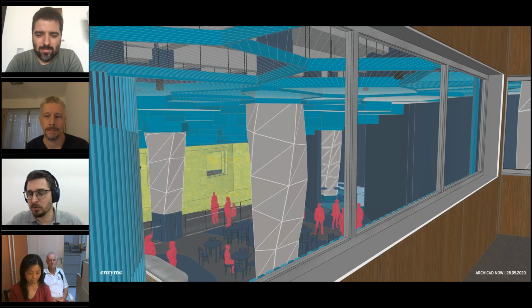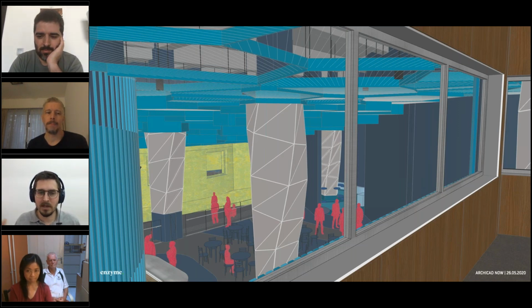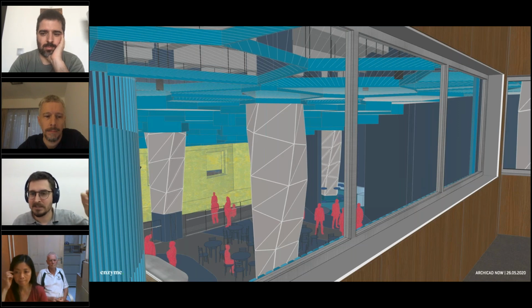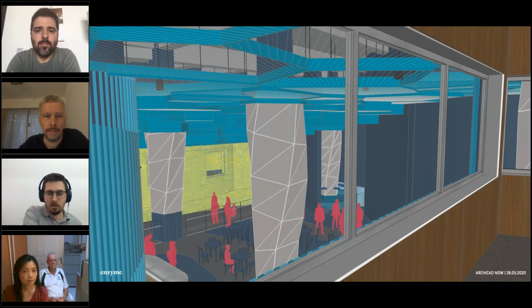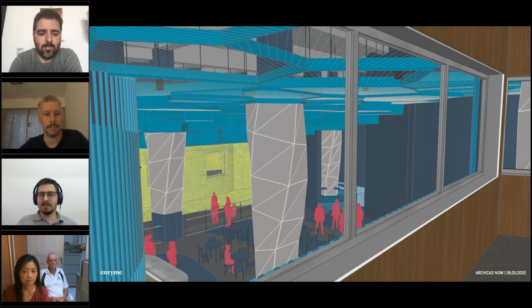But if you can check, I just wrote in the chat, this Elefront plugin is something that really helps. It's actually what they call the soft beam for Rhino, because you can also add properties to the Rhino elements, and therefore you can filter. You can create find and select sets in Rhino that will automatically read. For example, you say I want to link as a starting point the outlines that have this name or that are in this layer. So regardless if you have 1 or 10, or if that changed because of another script, those will always be pulled from Rhino. It's a find and select, but it's parametric, so it's kind of a live connection, right? Difficult to explain without an example, but I think we can invite you more often.